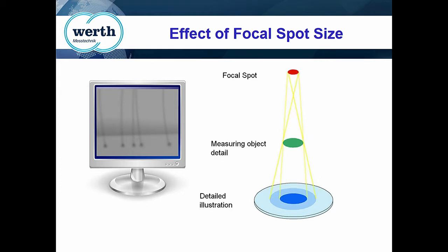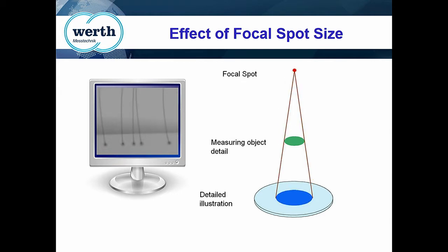And as you tighten that focal spot size, you're getting a clear image of your part. The one thing about computer tomography and X-ray machines is that this is nothing more than a very, very fancy camera. You can only compensate for a certain amount of overexposure, if you want to call it that.